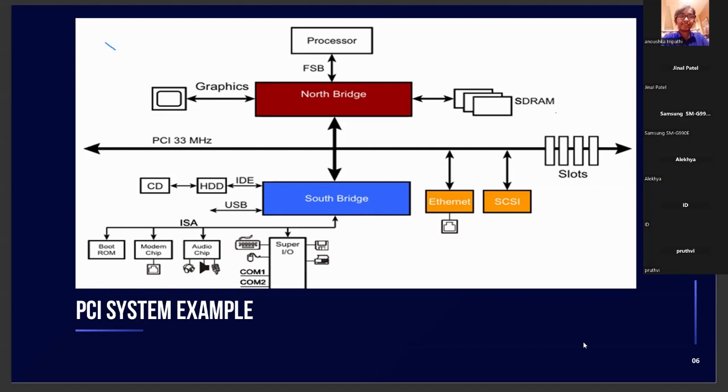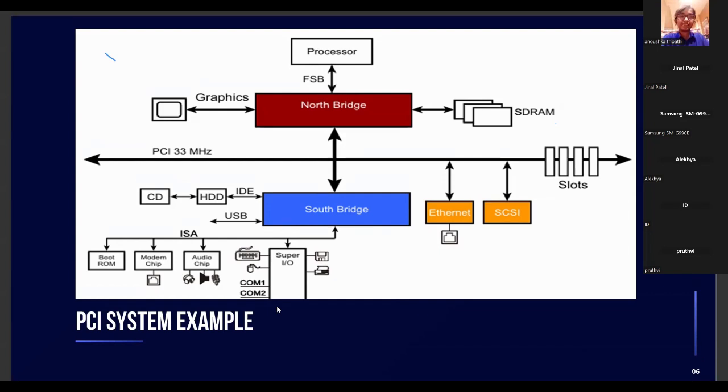So whatever communication you are going to do, whether it is USB, Ethernet, or whatever, it will go through this channel only. It will go to the PCI EP. The EP will determine whether it is a memory read request or write request. It will go to the DDR or whatever memory is in your device, take the data from there, process it, and send it back. Whether you want to do a read or write operation, the command is taken care of by the host itself.